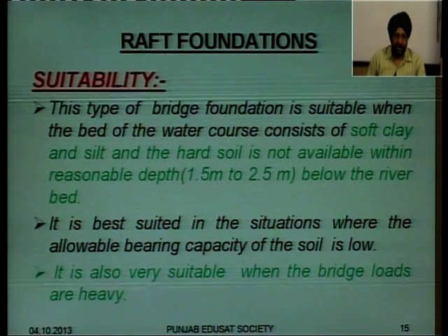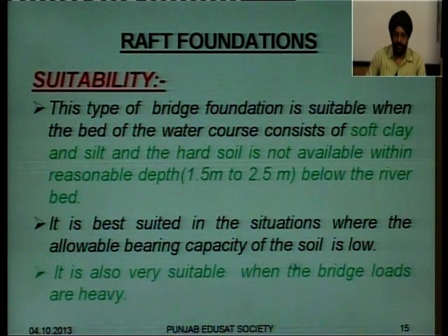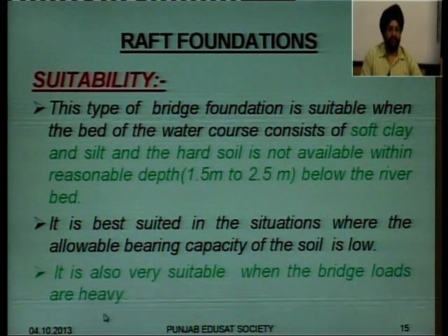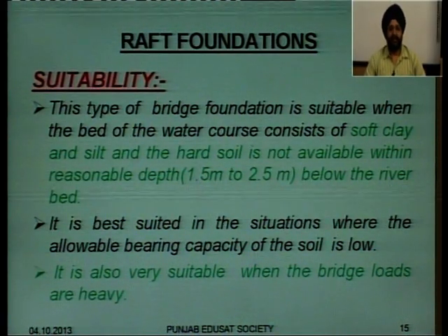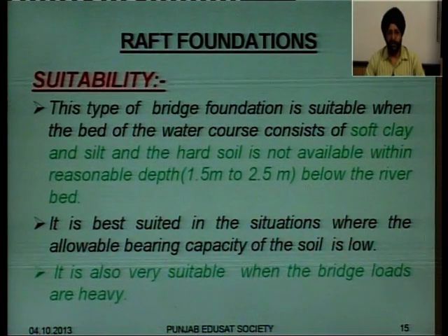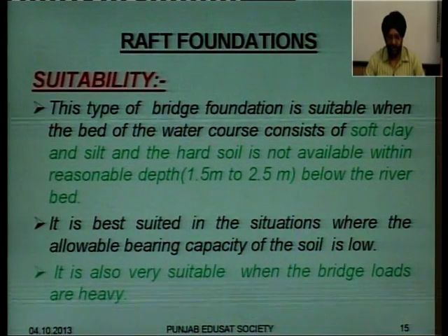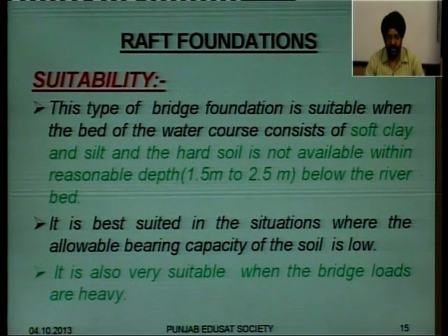Thirdly, these are also very suitable when the bridge loads are heavy. Once again, comparing it with the spread foundations, as I have told you, spread foundations are meant for the moderate type of bridges which are not very heavy, not carrying heavy loads.